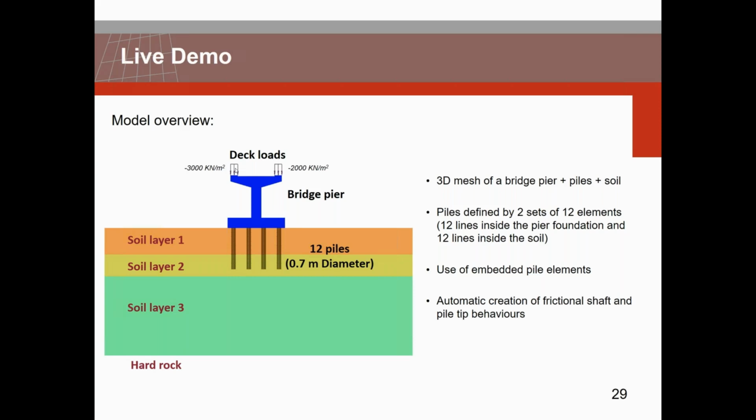During this analysis, we will consider 3 stages. First, the initialization, where only the 3 soil layers are active. Then we will add the piles and the bridge pier, and finally we will apply the deck load.